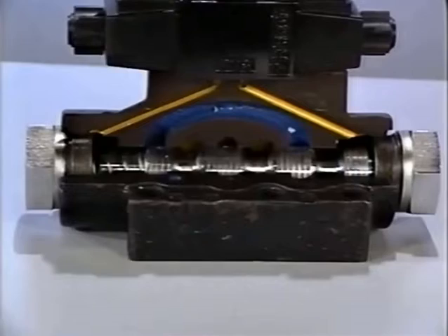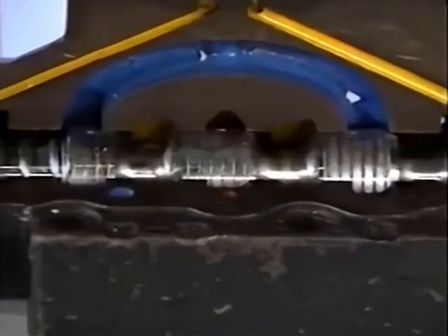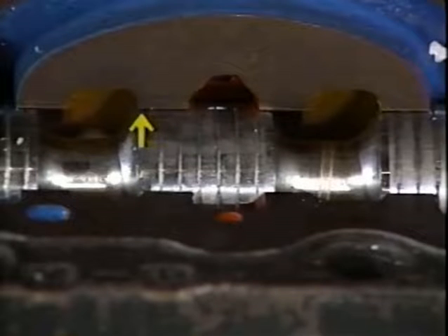Other valves we have seen generally permit more leakage than check valves because there are no seals between the various ports. The close fit between the mating surfaces is all that prevents the passage of fluid, and in many cases some leakage is actually required for proper lubrication of the valve as it operates.